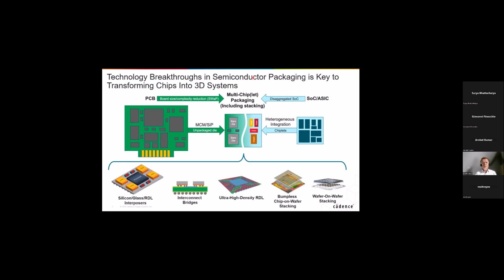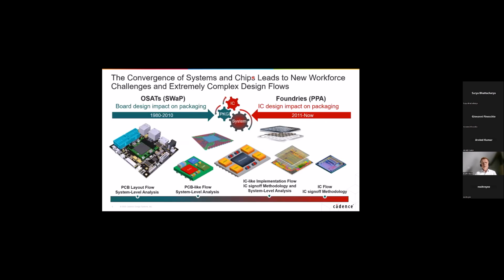or design tool. And for many years now, packaging is not only driven by the OSATs in the world, but also foundries coming up with technologies and going into this advanced packaging market, like TSMC with CoWoS, InFO, RDL type packages, and OSATs come up also with technologies competing with what the foundries come up with.